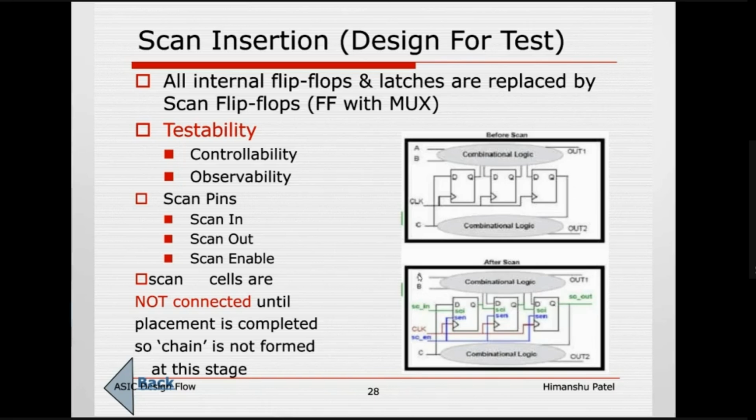Now you understand how the tool will think and behave for generating patterns or testing this logic. The tool will create opposite values. First, what it is doing is assuming a fault at that particular node and creating an opposite value as a pattern. Now, A, B, and C at a time, the tool can verify at a time, because the tool can assume the entire SOC to be tested in a single stretch, because that's a tool.